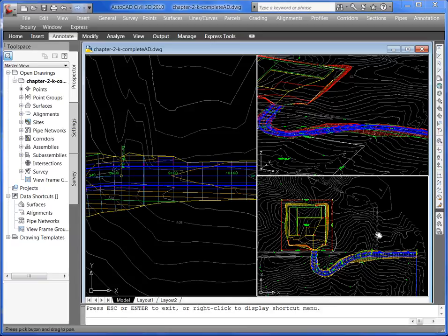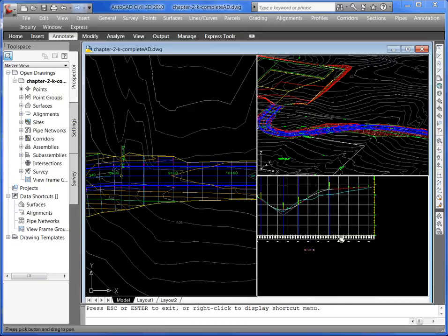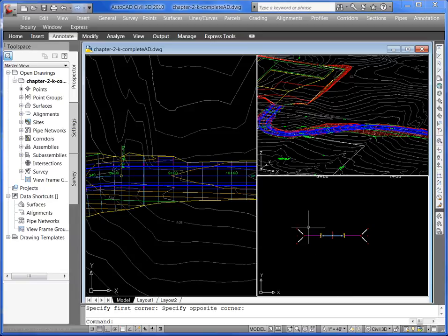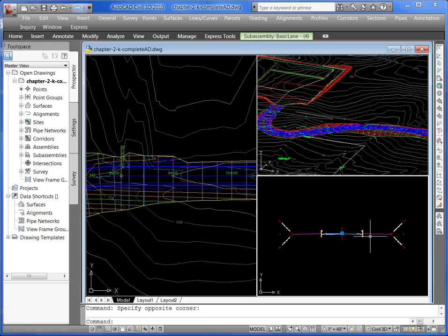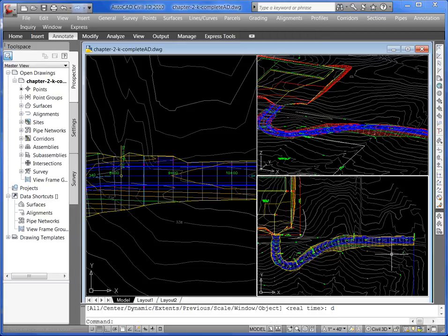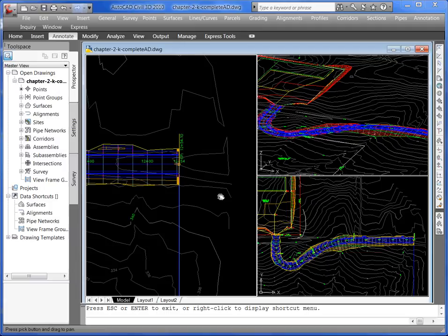The corridor's profile alignment is dictated by the horizontal alignment. And the final component for the corridor is the section, not a cross section. This is a section comprised of sub-assemblies. So this is an assembly, call it a template as well, and it's comprised of sub-assemblies. Now there were only a couple of you in exercise 2 that got to the point where you could create the sub-assembly, and that was a shame because I think it could have answered a lot of questions.